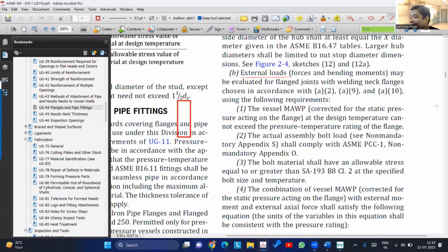To reduce pipe load, we cannot do that. We cannot reduce pipe load. So if I don't want to increase the rating, what is the other method? What can be the other methods? You tell me, where is the flange calculated? Sumit is saying qualify through FEA. What about others? Lagman is also saying FEA.